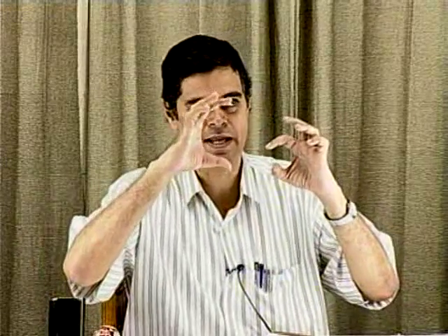Because you remember the case, when you are changing Vg, the position of the Fermi level at the surface is also changing. Under flat band condition, the Fermi level at the surface is in the same position as in the bulk. But as you make it accumulated, the Fermi level comes closer to the valence band edge for p-type semiconductor. As you deplete the surface by applying a positive voltage and the surface becomes intrinsic, the Fermi level at the surface comes at the center of the band gap.